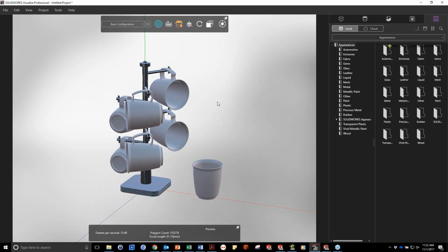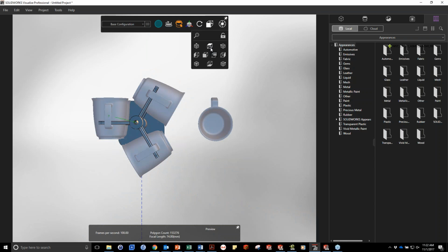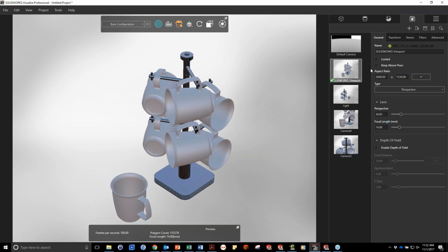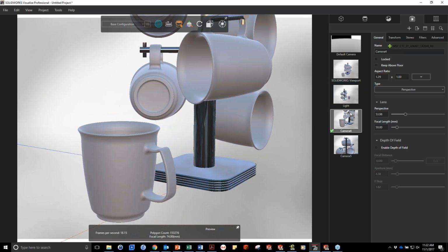If you haven't seen Visualize before, you ought to just install it. If you have SOLIDWORKS Pro or Premium, you can get Visualize Standard. It has really large buttons, easy to use on a touchscreen, no long scroll menus, plus a heads-up panel over the top. So you can do things like go through your standard views. It's pretty much tools you already know how to use. Isometric, you can lock your view focus. You could even do a fit to screen. And since this comes from SOLIDWORKS, if you've saved any views before, all of your saved views are available as well. Let's modify this a little bit.